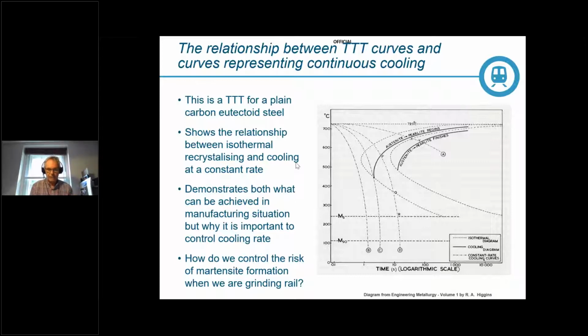And the colour of the steel as it cools indicates the temperature it has been subjected to. So if it's turned to a dark blue colour, that we call bluing, it's indicating that we've got excessive heat in the surface. This will be quickly chilled by the cold rail underneath, and we end up with martensite in the surface layer, and hence the risk of cracking forming.